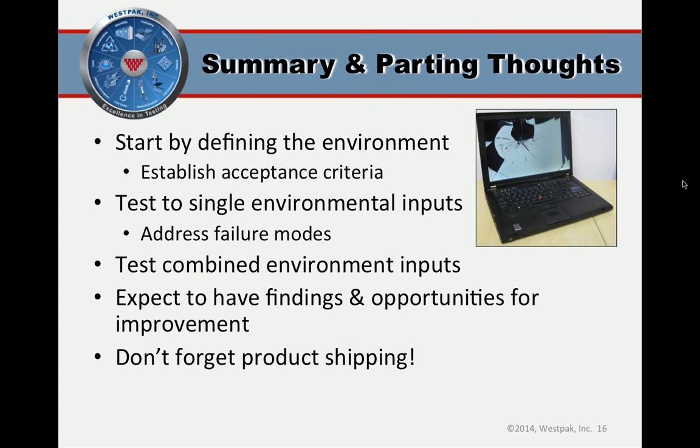And lastly, don't forget about shipping your product, especially for larger capital goods, so things like 19-inch server racks or big capital communications or medical equipment. Shipping is often the most severe environment the product will see, especially the installation portion. So when you get to the end point, you uncrate, you install, that's where you can see problems.